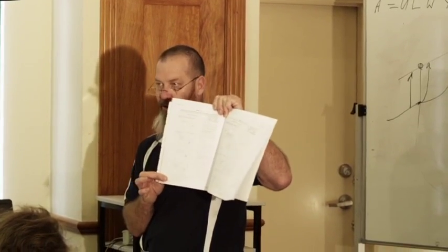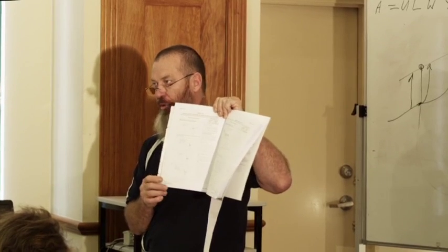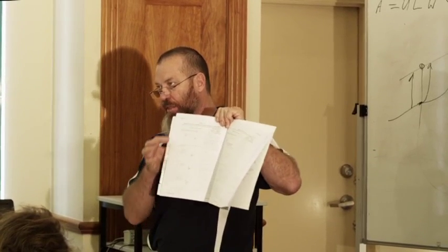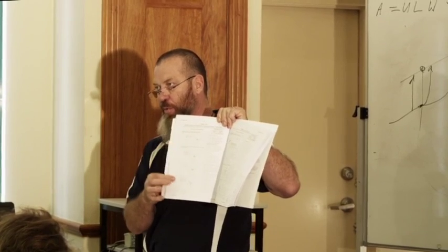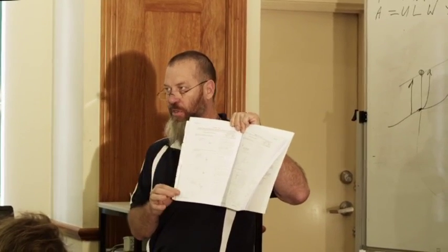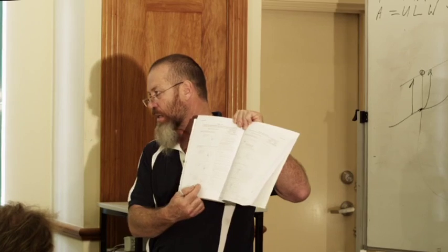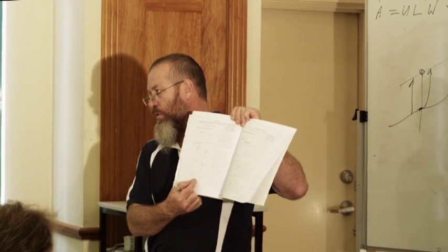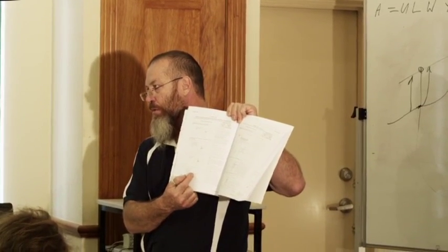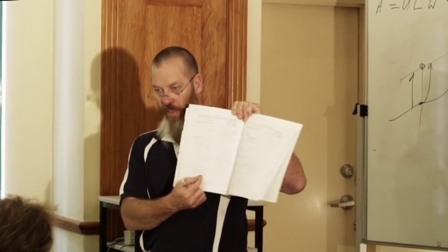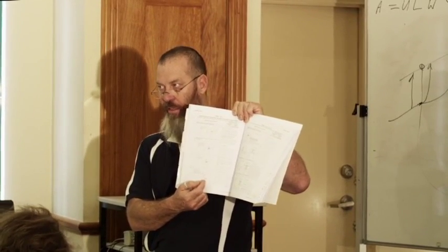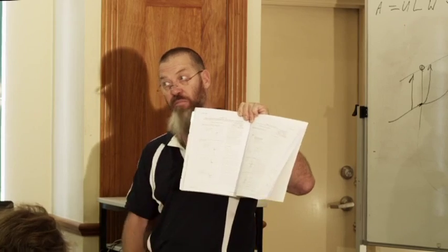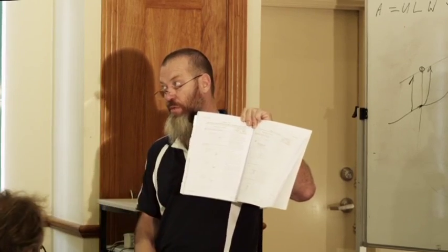And Type D is my favourite one. Where I can get away with it, I'll use Type D. Has the same resistance as B and C of 2.9 kilonewtons in its bog stock form, but it actually takes care of 2 connections. In Type D, you're doing rafter to plate and plate to stud because you're connecting it down there. That's why I like using it. Money in my pocket. 2 connections for the price of 1.